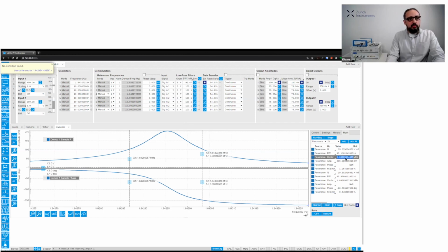Now I will actually drive it at the center frequency. So now look at the level of the ADC. This actually shows that we have 400 millivolt input range, and we are only occupying just, I don't know, 10% of it or so. If I start driving this at the resonance, you will see that we actually have much higher amplitude because it is now amplified.